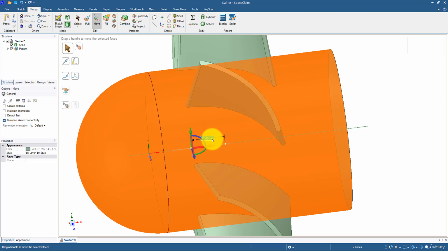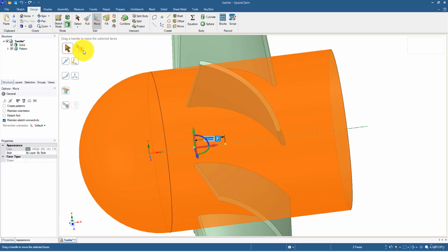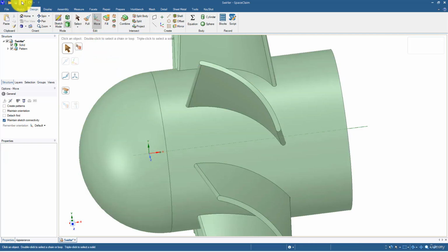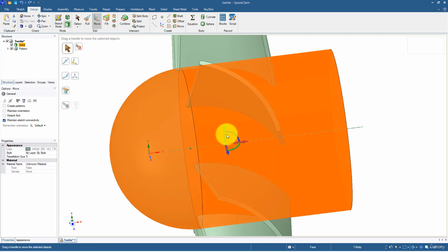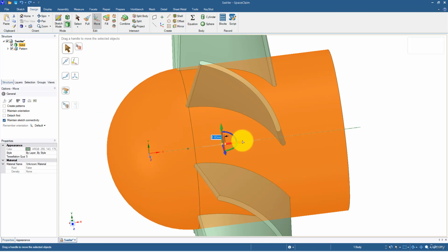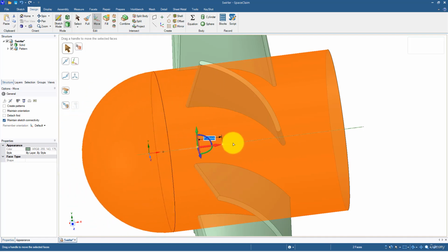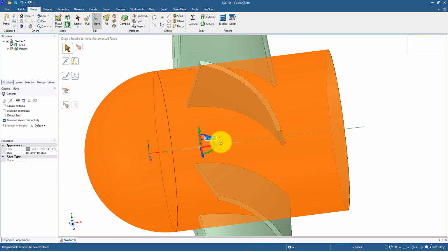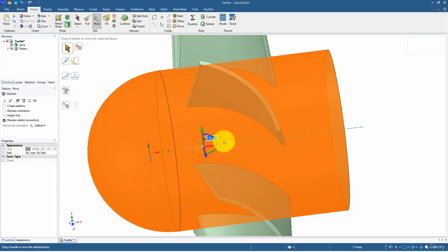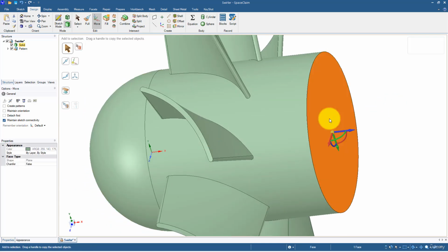This is the one option. This is the second option, in fact. So either you can use this whole solid body movement if you triple click here, or you can use the double click, and this will increase the length of this solid body in this direction. Or if you want to reduce the length, then you have to move in the positive x direction, and to increase the length you can move in the negative x direction.